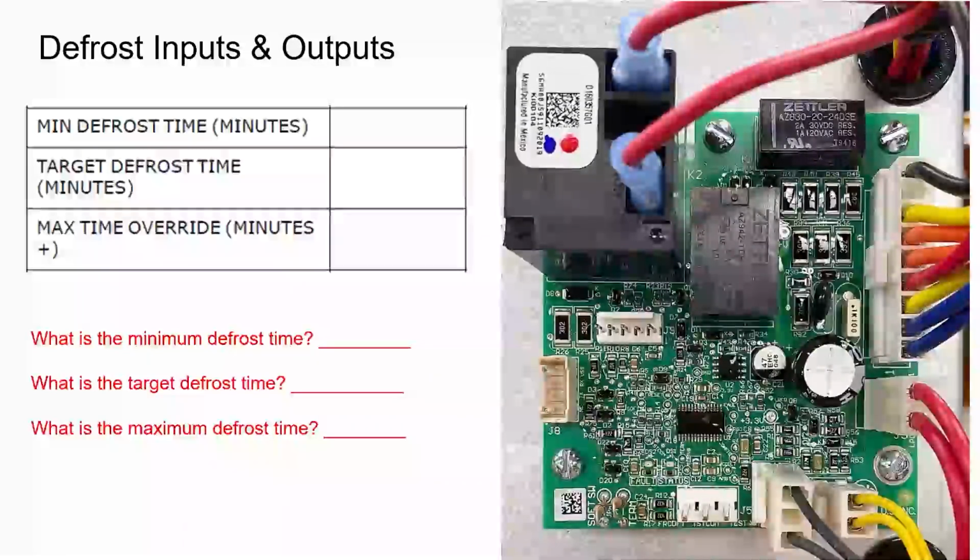Now, target time for defrost depends just a little bit on some setup configurations, but normally we're shooting for about 3 to 4 minutes in defrost. And the board has an algorithm that watches that timing and it starts to adjust the coil temp and outdoor temp sensor set points for defrost to try to target that 4-minute defrost.